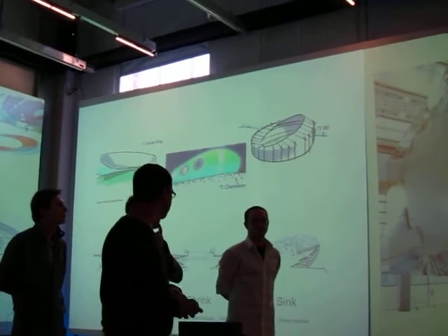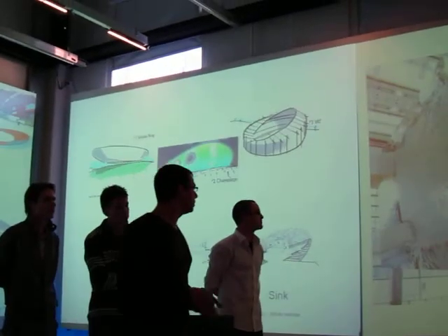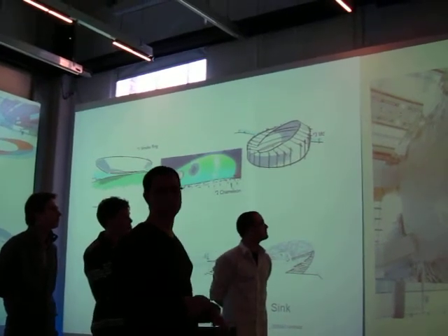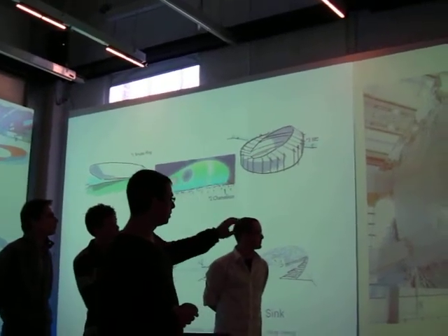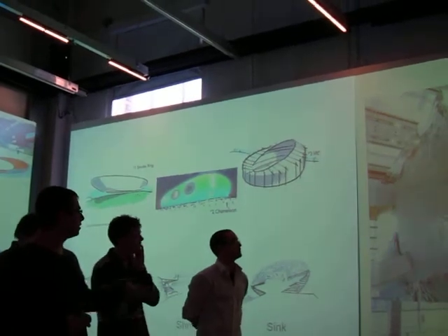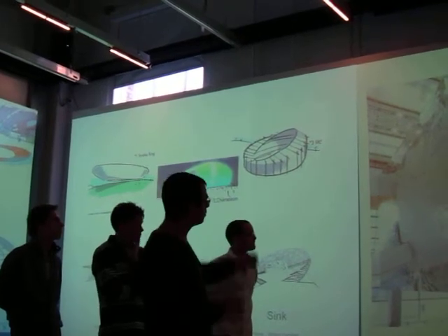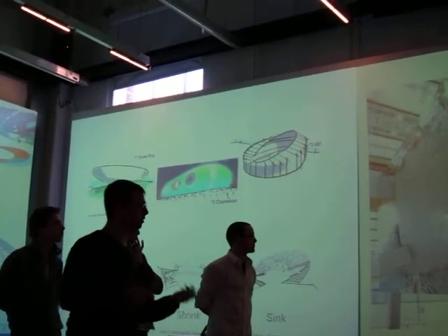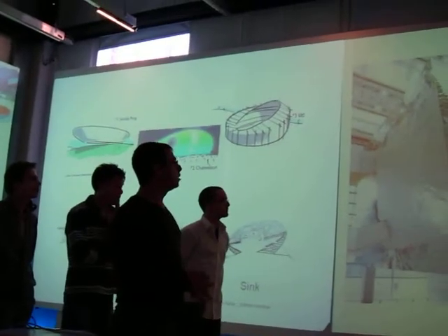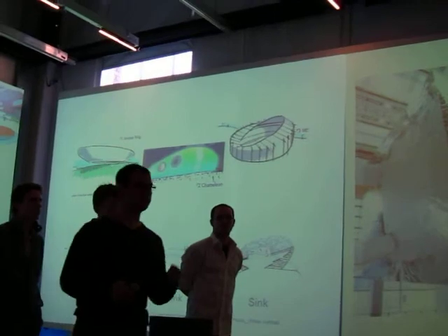I would like to start with this example by a Japanese architect named Ishigami. This is neutral buoyant aluminum construction filled with helium, which is in a museum. Where is it? In the Museum of Modern Art in Tokyo. Was. And it's fixed at a certain height, calculated by the weight of its own construction and the buoyancy of helium, or the ratio between helium and air density. We found that roughly you need 1 cubic meter of helium to lift 1 kilogram.